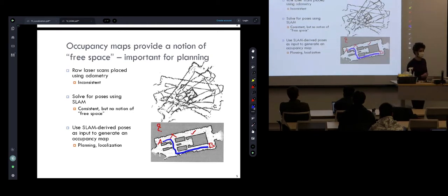Now, what if somebody is moving in the map? Or at the time that we mapped the environment, maybe it was empty, maybe now it's not, when the robot is navigating. And that's very important. The environment can be dynamic and not necessarily static. For example, maybe this is a museum. We have an example of a museum later. Maybe you map the building when it's empty, so that you save the map, and the robot can navigate at a future time. But when we visit, maybe there is a group of people visiting the museum, and it's not as easy as moving from A to B freely. So this map, as is, is not capable of modeling a dynamic environment. There is also an assumption, as we will see, that the environment is static. So the world is static, and then we infer this map. This is a built-in assumption of this method.